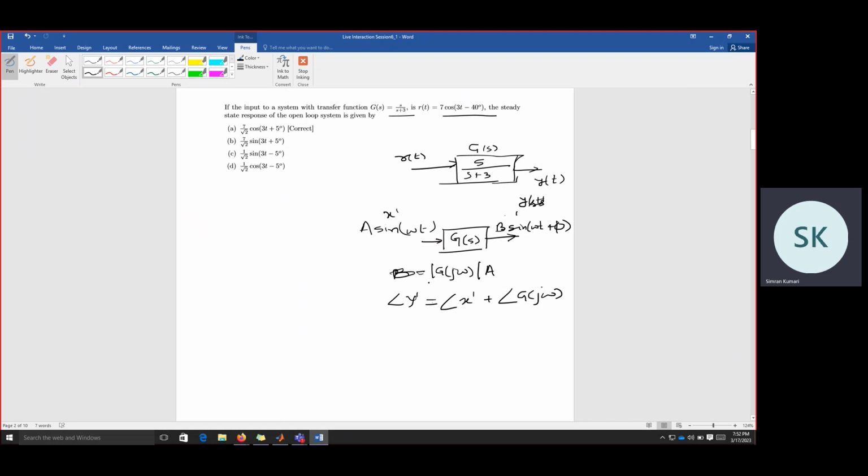Okay, so one thing that we can do is find the Laplace transform of this input, and since this is the input to this system, the output Laplace transform will be Y(s) equal to R(s) into G(s), and then we'll take the inverse Laplace transform, and we can find the response of this system G(s) corresponding to this excitation.